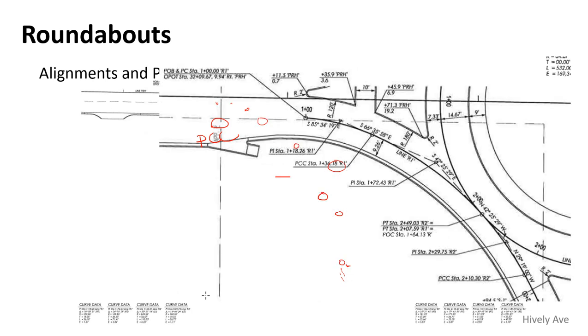And here's an example. I don't know why it doesn't erase when you move forward, but I can erase that. All right, so here's an example. You moved in, here's that PCC, and then we've got another curve, and then it finally hits our point on tangent, and we hit tangent to this circulatory roadway alignment, which comes through here. Every one of these alignments has the bearings, it's got stations to it, it's got all that right through there. Oh, here's the end of the splitter line. Look, I used the 2-foot radius, which matched what the informational guide said.